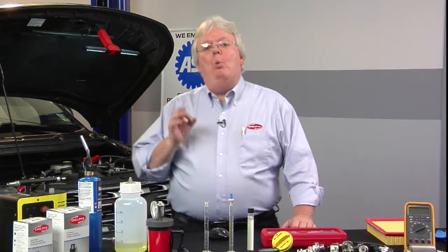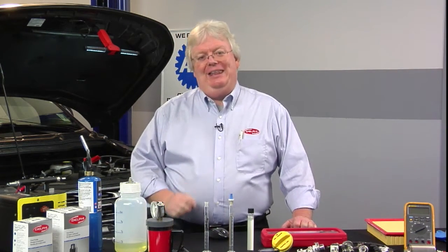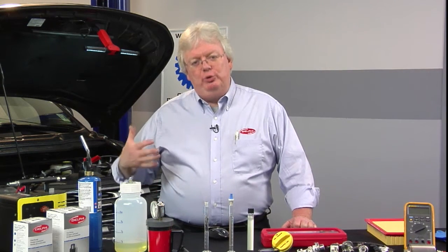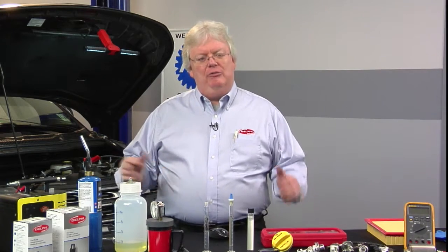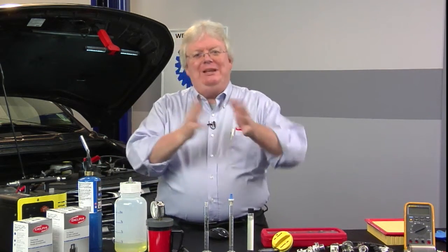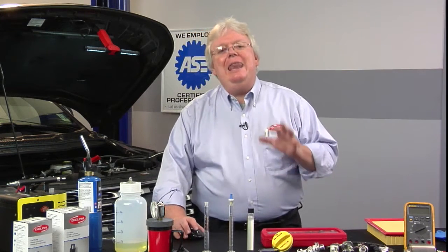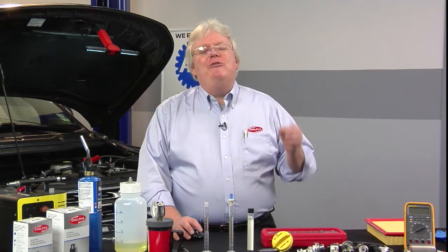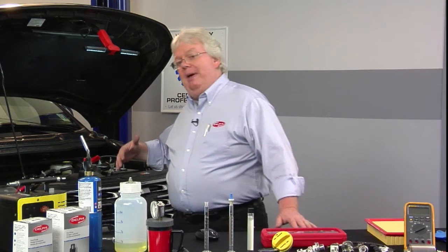Now we have the new wide range air-fuel sensors on this vehicle before the catalytic converter and switching type O2 sensors, conventional voltages you'll see after the catalytic converter. So we're not going to really see the actual 0.1, 0.8, 0.6 volts of O2 like you may be more used to seeing on older vehicles.